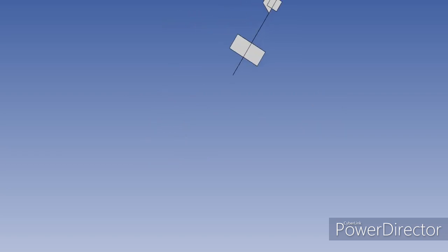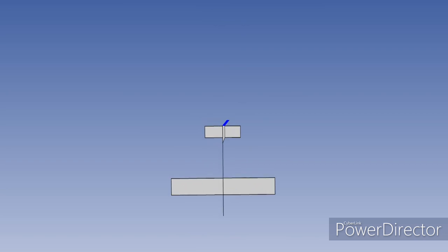The fourth use of the rudder we will look at is spin recovery. Full rudder must be applied in the direction opposite to that of the rotation of the aircraft. In this case, rudder to the left.